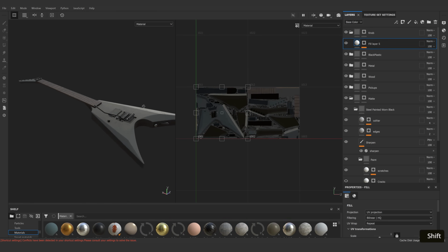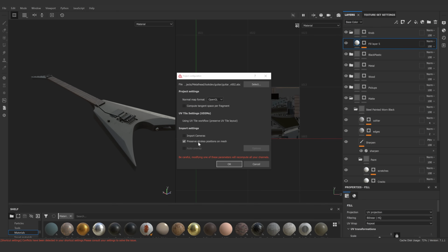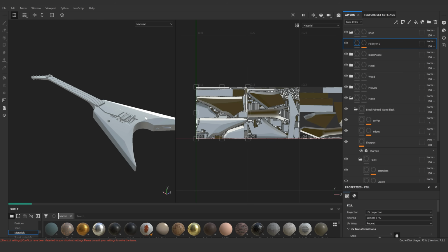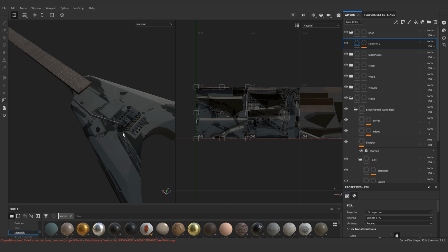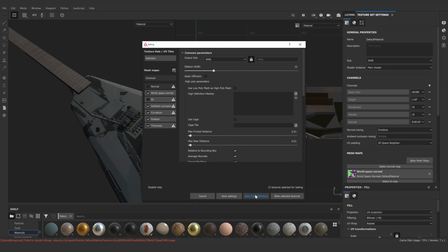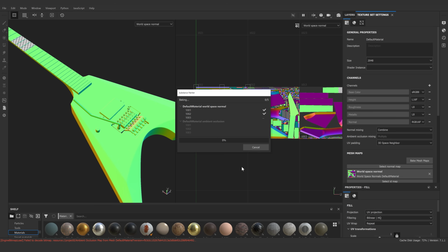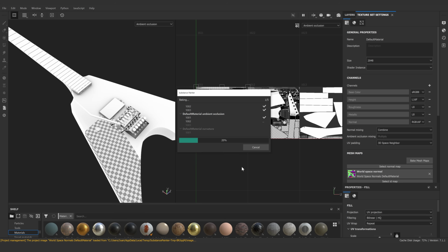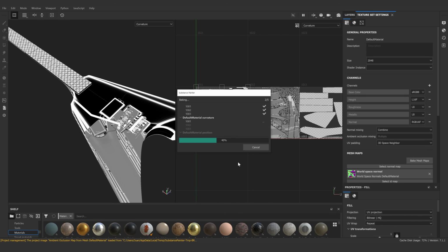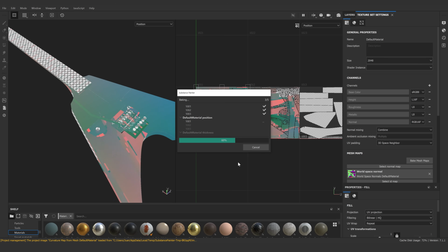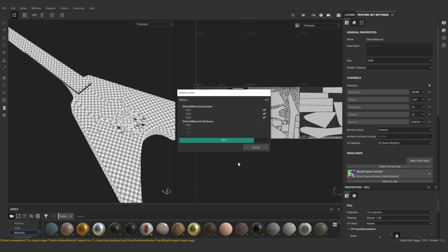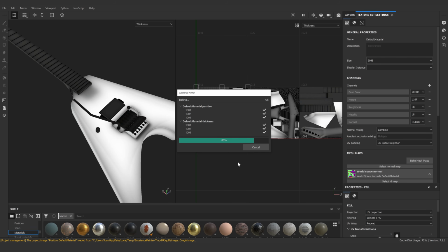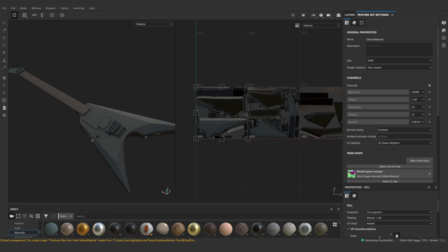You can freely change your UV layouts to occupy more UV space, switch it with the old model, and keep all the texturing work you did so far. This can be a lifesaver as you don't have to worry much about UV changes. In fact, especially for commercial things, I never worried anymore about big changes even after textures were done, because I knew I could update my UVs, recalculate all the paint work, and go on with my project, which is actually pretty cool.